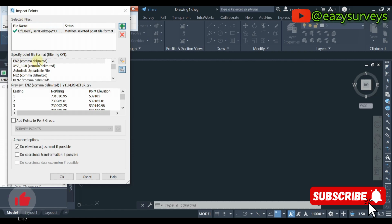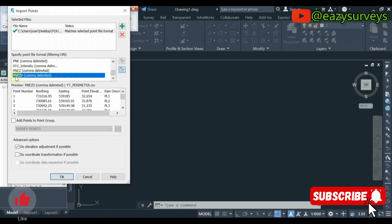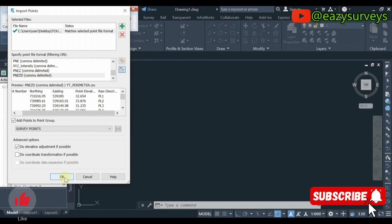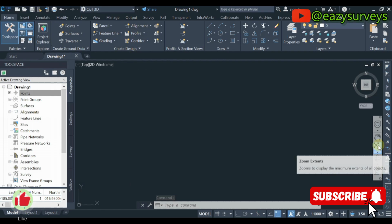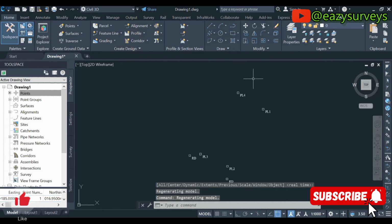Then you come to this specify point file format. Then you choose the way your data is arranged on Excel. So what I have is point, which is the ID, northings, eastings, and elevations. So here it is point, northings, eastings, Z for elevation, D for description. So you can see here point number, northings, eastings of my data, elevation of my data, then the description. All right, then you check this box for add point to point group. Click on that. Then you click on OK. So that's just it. Then you can close this window. Then you can come here to zoom extent. So here is the survey data imported directly from Excel to Civil 3D.